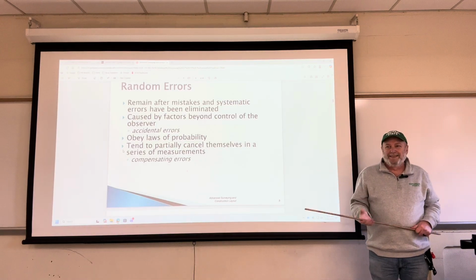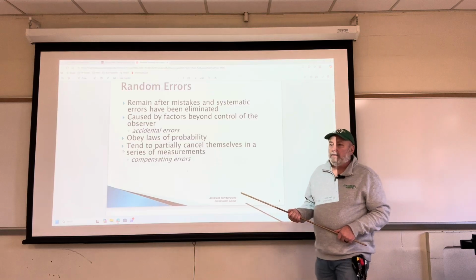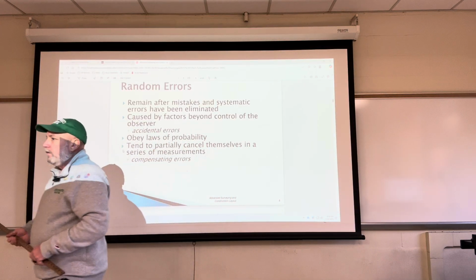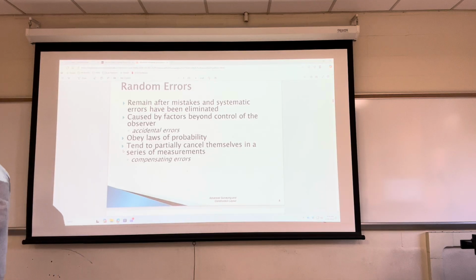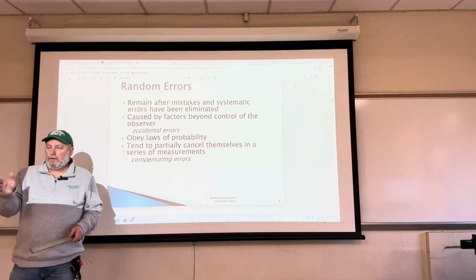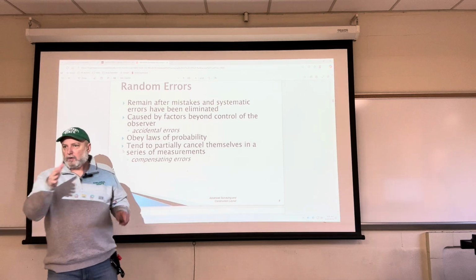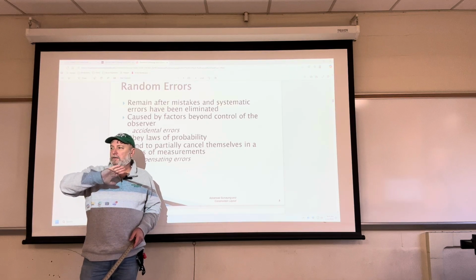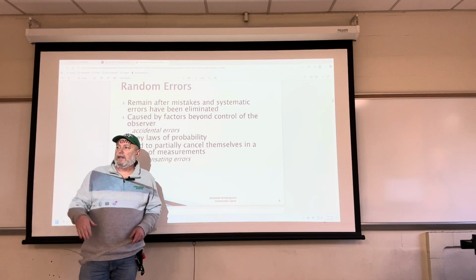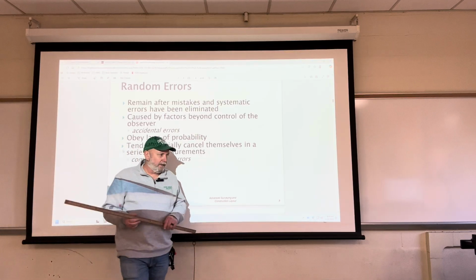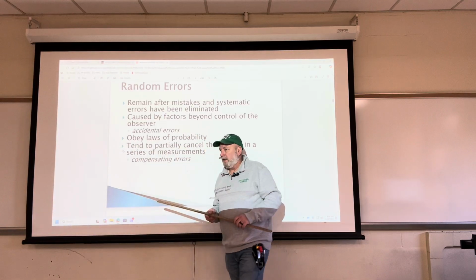Is that what it's doing when you turn rounds? Like on the total station? Yes. On a total station, when you're turning rounds, you're measuring your angle with the scope in a normal forward position. You flop the scope over and sight your backsight, foresight again. That's trying to take care of the compensating errors.